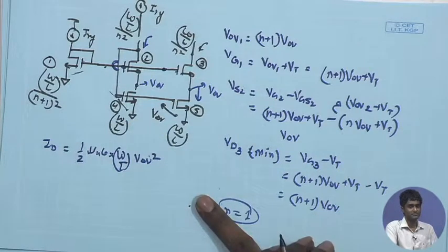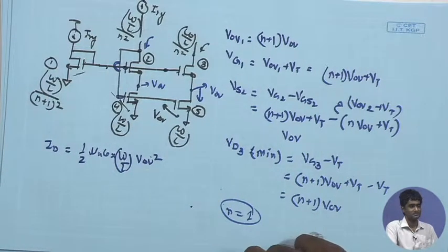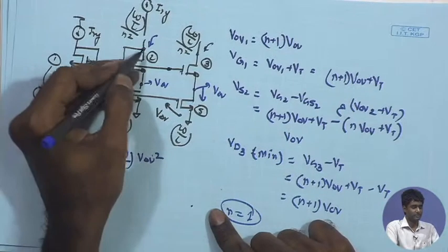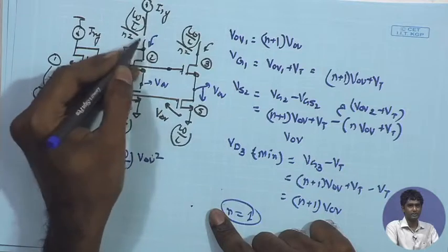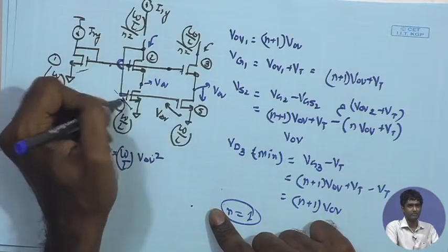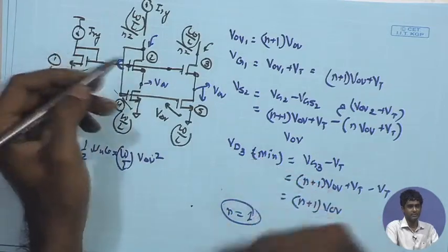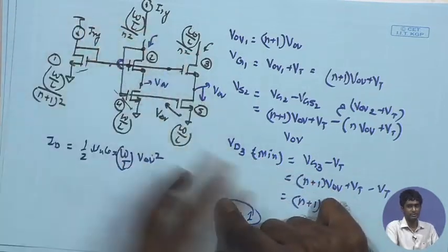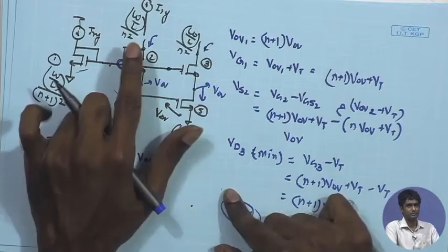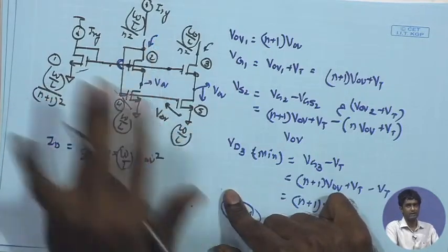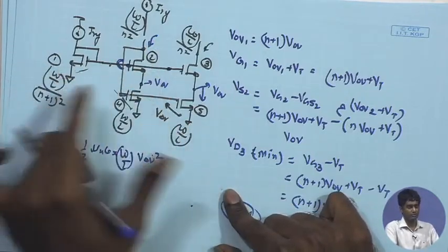Why? Yes, tell me. Now, if you put a test voltage over here and you increase that, what is going to happen? VGS is going to change, and therefore the small signal current will be gm VGS. Therefore, you are going to have the current change corresponding to 1 upon gm. So, in this branch, you are going to have impedance very low, 1 upon gm.